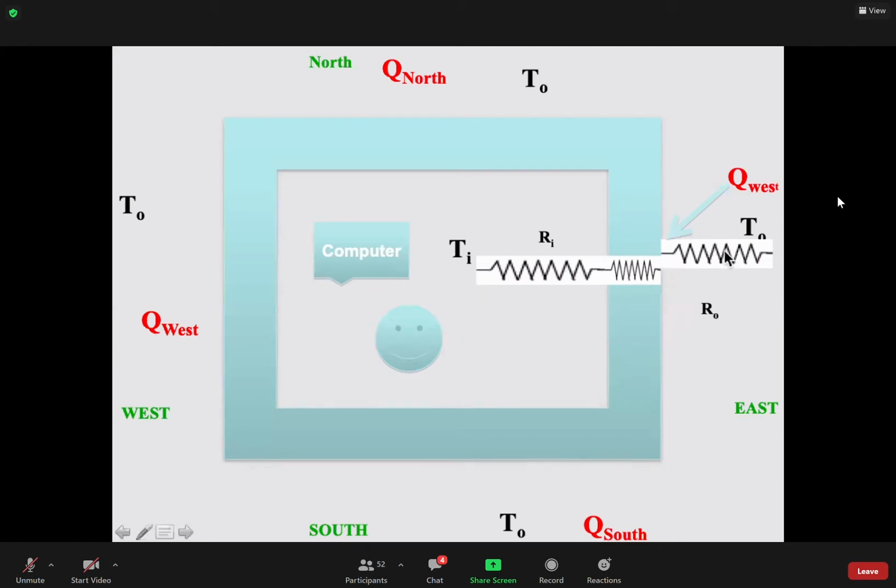Now remember you have a thick wall, I believe it was around 40 centimeters. Therefore, the solar radiation that comes here will not immediately affect the temperature inside the room. If you look at the result of your project number 1, you will see as the temperature increases here, the temperature in the wall increases immediately. But in reality, there is a lot of mass here, and some of the solar radiation will change the temperature of this part, and a portion will go through here and so on. Therefore, it probably takes some time.